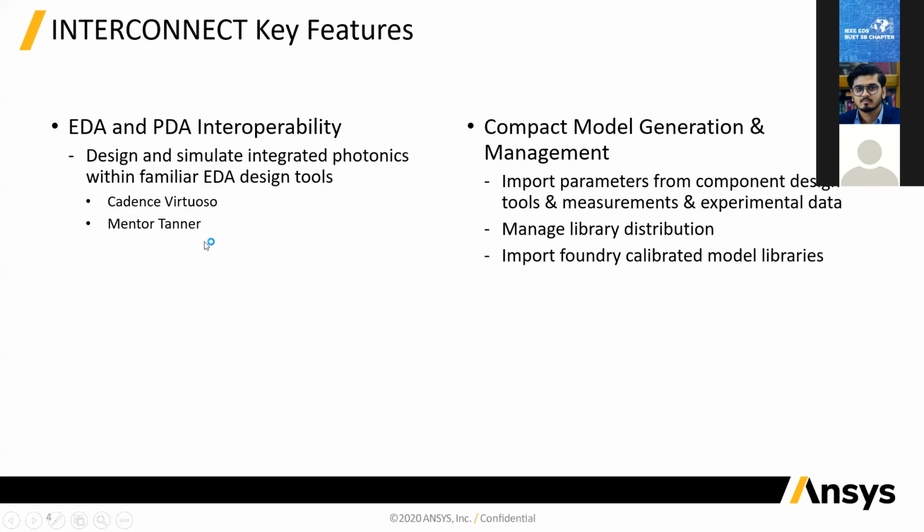This is what I was mentioning, that when you're running simulations for a photonic circuit, often you have active devices in there, and in order to bias the active devices, you need electrical drivers. So in many cases, you want to actually run an electro-optical circuit simulation where you want to model the drivers driving your photonic circuit simulated in an electrical solver, like a SPICE solver, either in Cadence or Mentor Tanner.